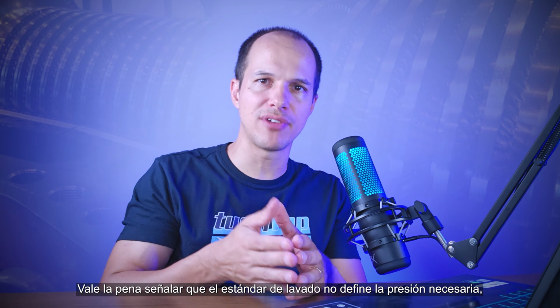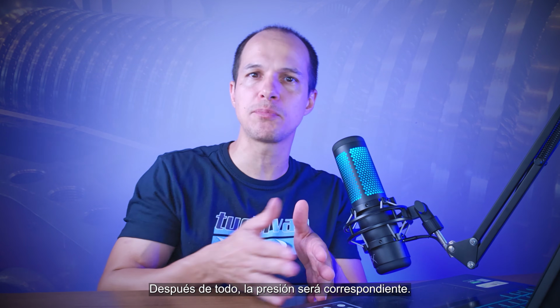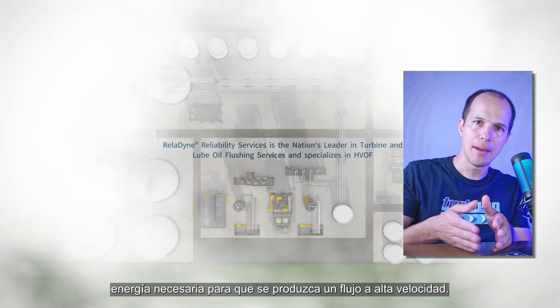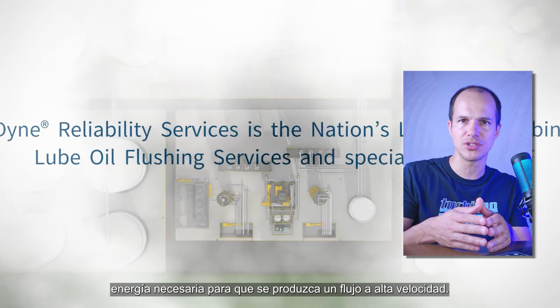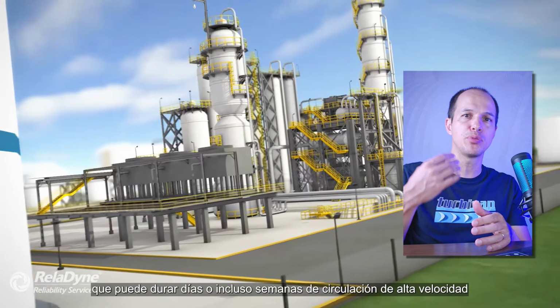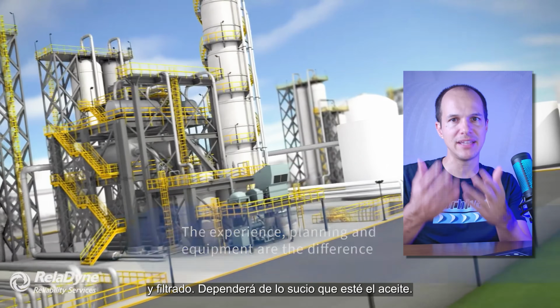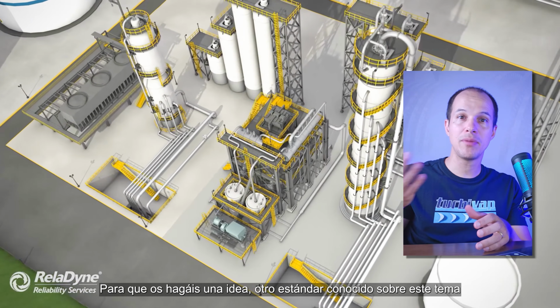It is worth noting that the standard on flushing does not define the necessary pressure. Nor could it. After all, the pressure will correspond to the energy required for high-speed flow to occur. The entire flushing process can be quite time-consuming, lasting days or even weeks of high-speed circulation and filtration. It will depend on the level of dirt in the oil.